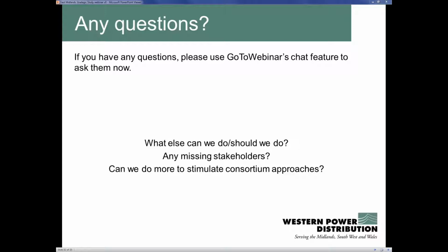So in terms of how we've used that data, on a lower level, we have aggregated up the rooftop PV figures and split them down into what type of output those particular generation technologies would have on the net residual load or demand that we will find at each of our network exit points.